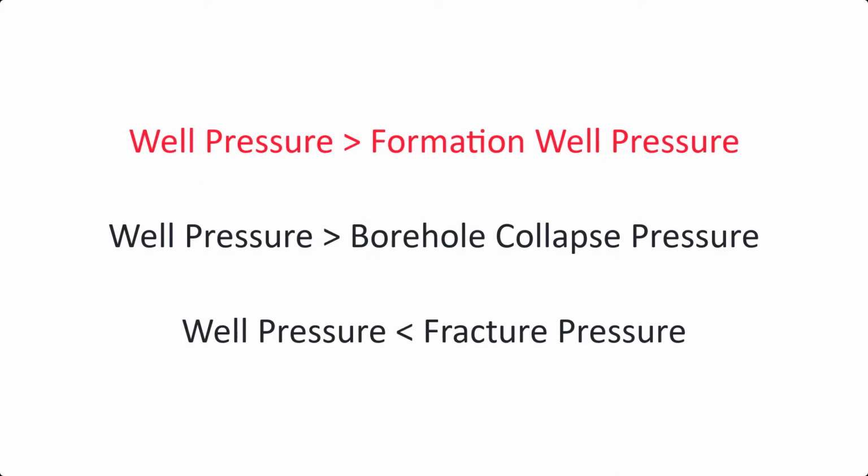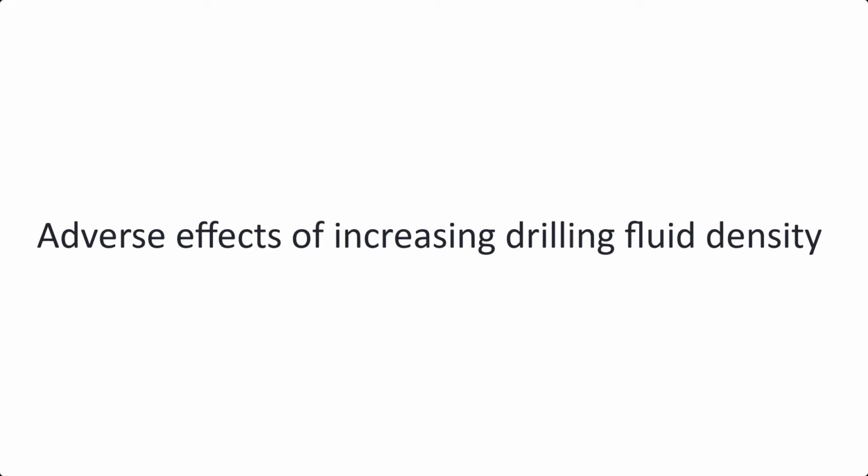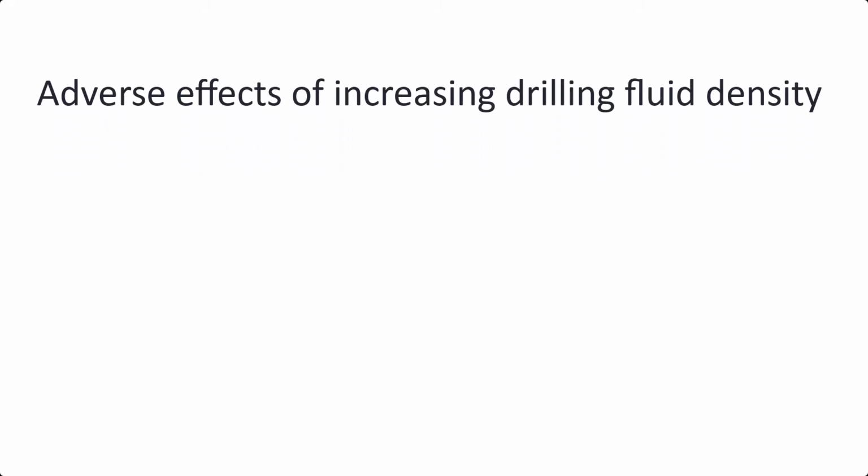In order to control the formation pressure while drilling, the pressure of the fluid in the well should be greater than the pressure of the fluid in the formation. The borehole wall is supported by making sure the well fluid pressure is greater than the borehole collapse pressure. In order to avoid lost circulation, the pressure of the well fluid should be less than the pressure which would fracture the formation. There are some adverse effects when you increase the drilling fluid density.